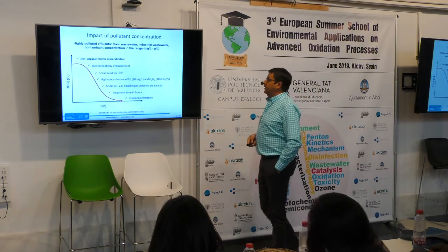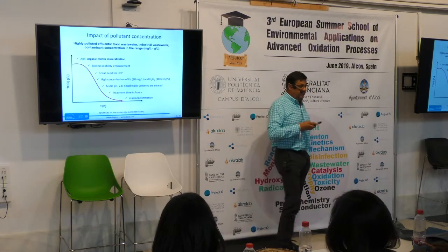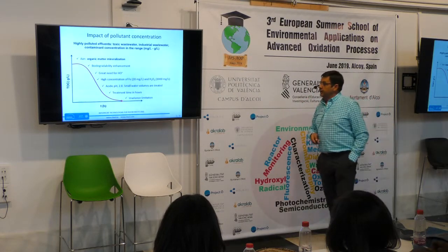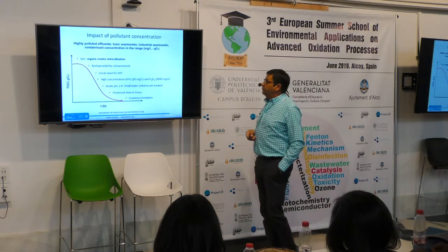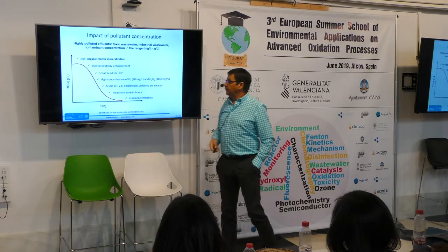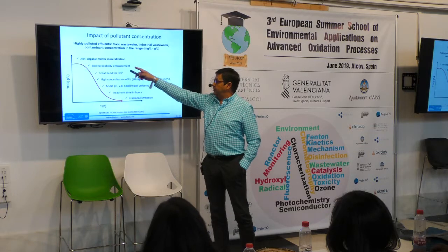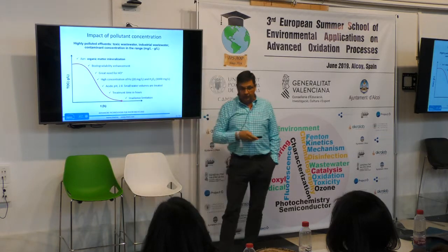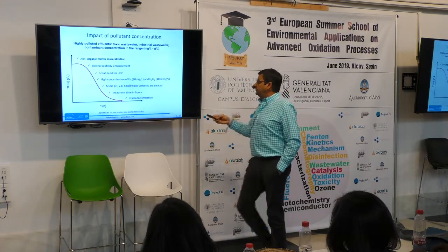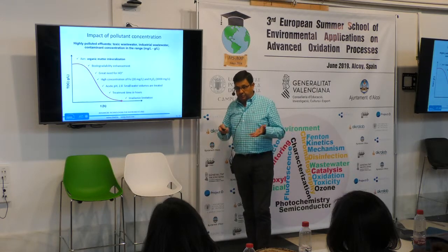Now, let's speak about the impact of pollutant concentration. This is very, very important when speaking about photo-Fenton process. When we are dealing with highly polluted effluents, that is the case of toxic wastewater or industrial wastewater, the aim of the treatment is commonly the mineralization of the organic matter, along with the enhancement of biodegradability, because the complete mineralization is not possible.